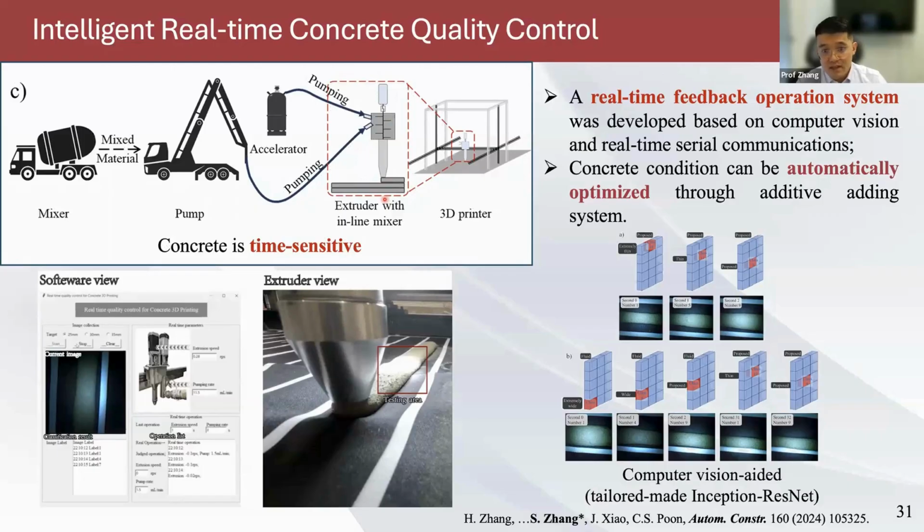So concrete is a time-sensitive material. Even though you want to control it, for example, we can control the concrete status using different accelerators, retarders, etc. The amount of accelerator, for example CO2, that you put into the concrete should be dynamically changed because the concrete is changing over time.